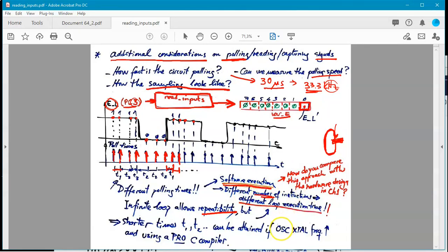So this is fundamental, because here you have a kind of repeatability thing. You get samples continuously because the loop is executed constantly, but the samples come at different times. You cannot imagine here something that was a must in chapter 2, a perfect sampling frequency related to the clock. Here you don't have the clock anywhere. You have the possibility to get values from the inputs, but the values are not sampled synchronously with something resembling a clock or the like.